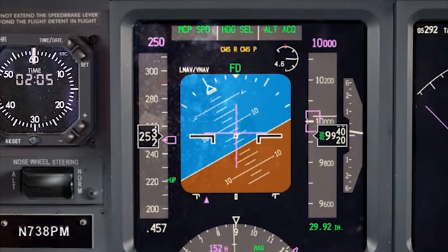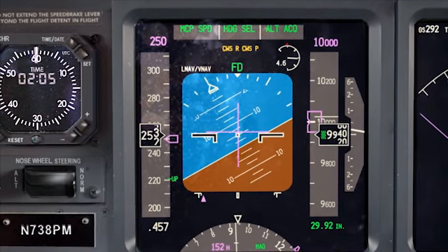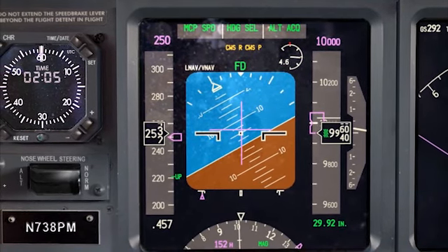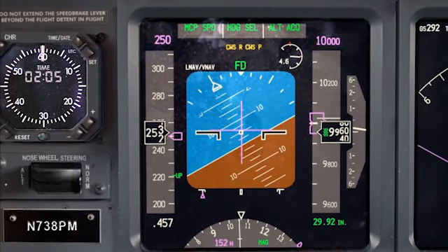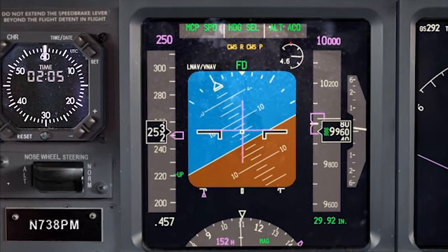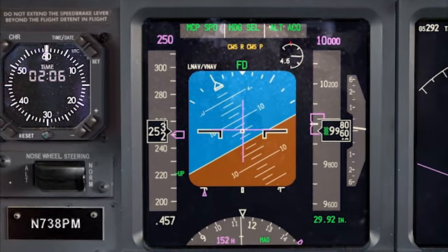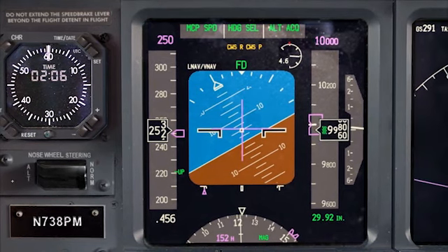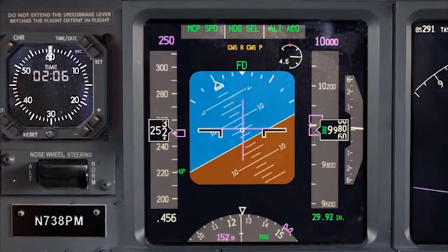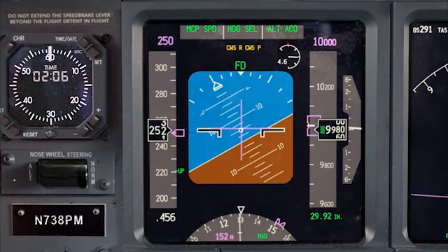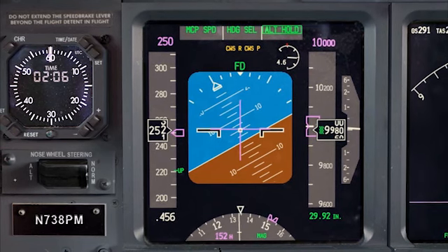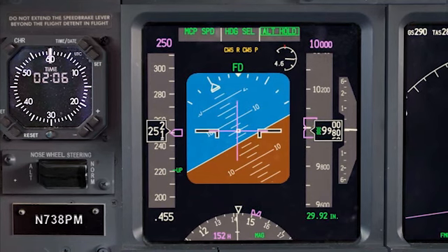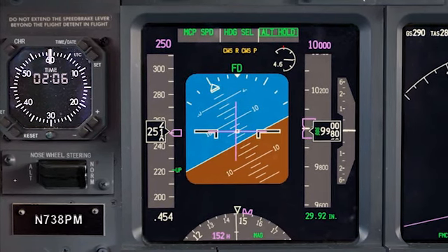Unlike flight director, the autopilot actuators are working to keep the flight attitude the pilot has set using the control wheel. However, unlike the autopilot, the system will not follow continuous changes. It's a set it and stay command. Just imagine, if you will, telling your airplane as you would a dog, sit, stay. That's what CWS does. It won't move, it won't adjust, it simply stays put.